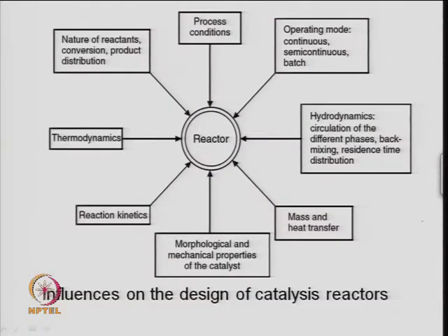What we look in a design of a catalytic reactor, again, is whether it is a homogeneous or heterogeneous system. So, the reactor design depends on the process condition, that is the first thing, in terms of the temperature, pressure which is required, nature of the reactant, the conversion which is expected, product distribution, that is important, thermodynamics of the process should be known, reaction kinetics in terms of the micro reaction kinetics well known. Then we need to understand the morphological and mechanical properties of the catalyst, which will be placed inside the reactor.